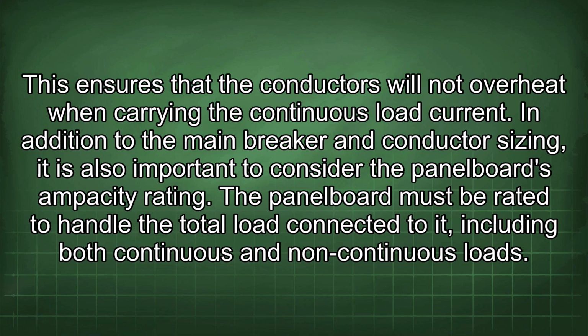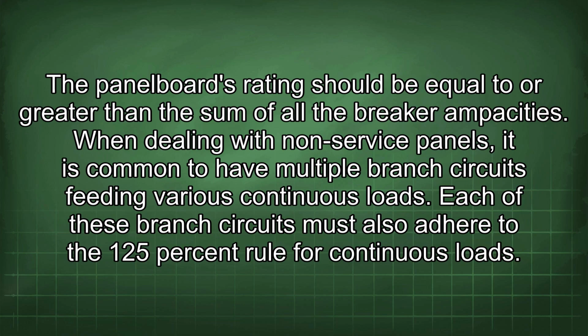In addition to the main breaker and conductor sizing, it is also important to consider the panel board's ampacity rating. The panel board must be rated to handle the total load connected to it, including both continuous and non-continuous loads. The panel board's rating should be equal to or greater than the sum of all the breaker ampacities.